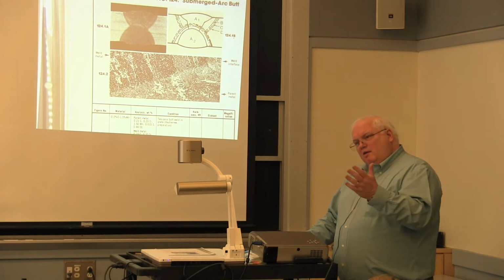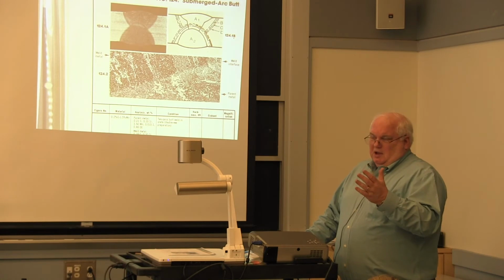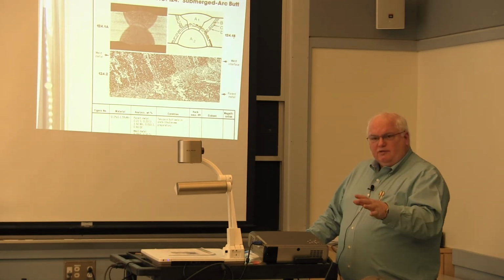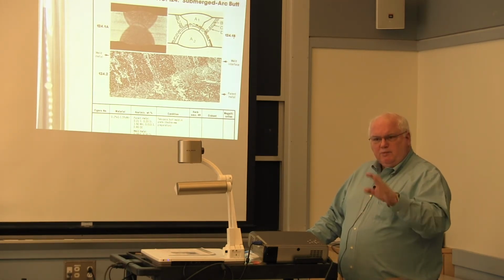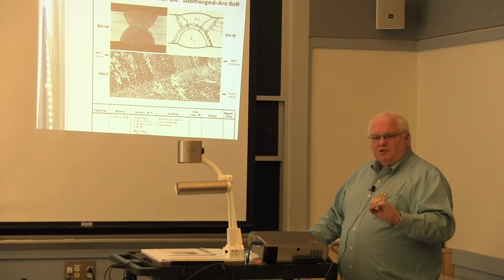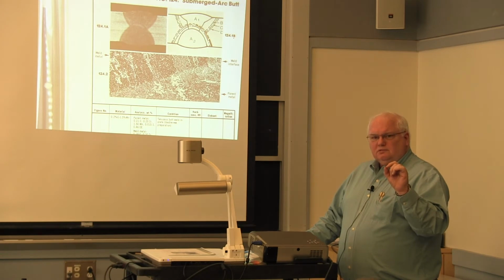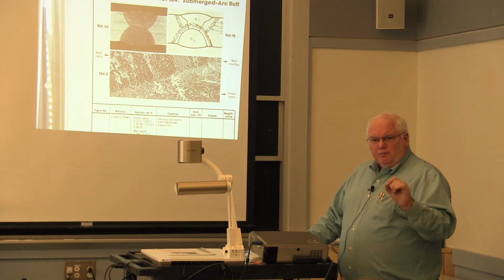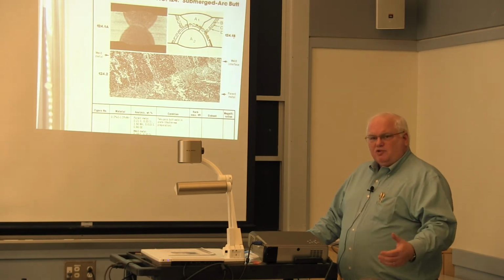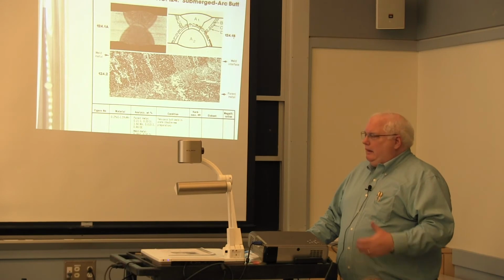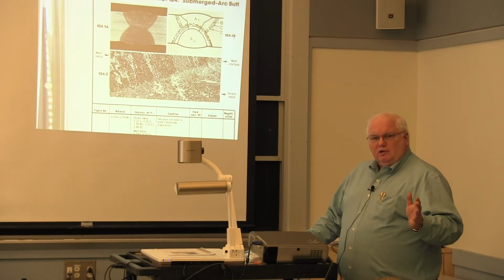Okay, and that doesn't matter. It doesn't really matter whether it's slow tensile failure, slow bending, or whether it's impact fracture. The impact fracture also, the deforming area or the deforming volume decreases if the weld's weaker, and it will absorb less energy in an impact test. So whether it's dynamic fracture or whether it's slow fracture, undermatching is not good.